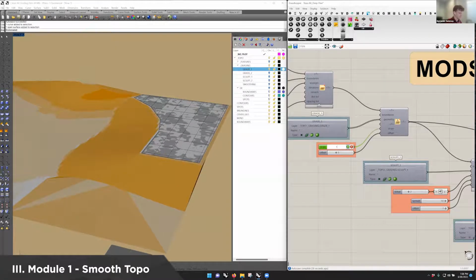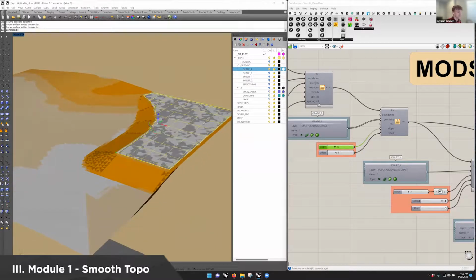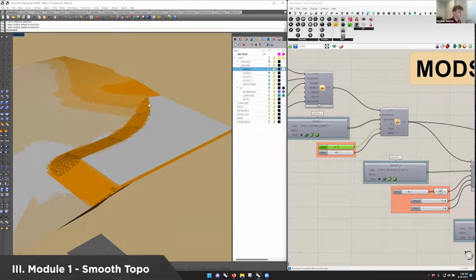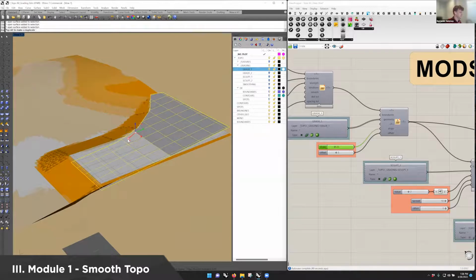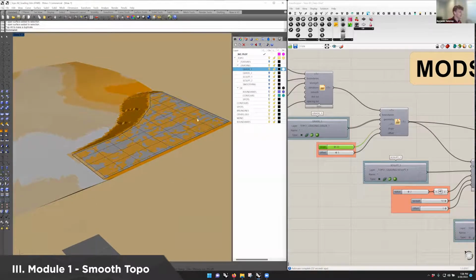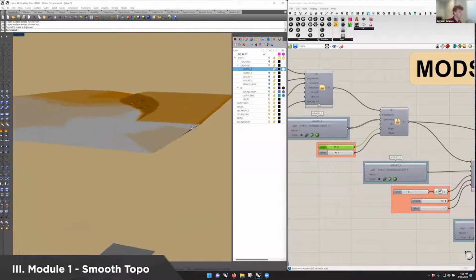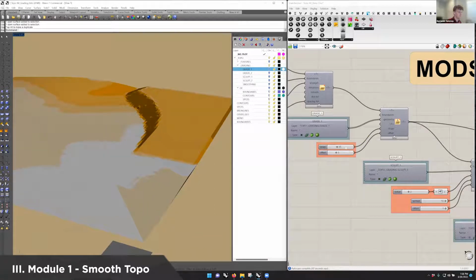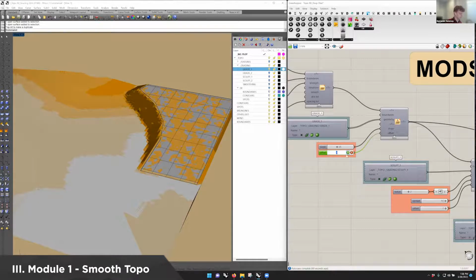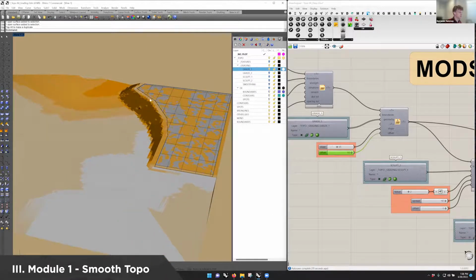But it really allows you to define exactly what you want to do in terms of the slopes grading away from that. It will read that geometry whether it's planar like it currently is, so it's creating a flat plane at the very top of where I placed it, but I could also angle it a little bit and it will regrade it at an angle and create a slope down like that. And then any parameter that I change will also readjust everything accordingly. And then I could also increase the offset too. And so if you see where this surface is located, if I increase this to 10, you'll see that the space away from the surface becoming flat is also being included in that.